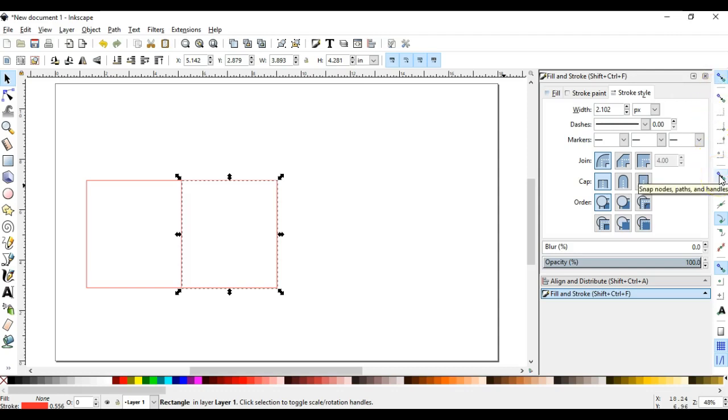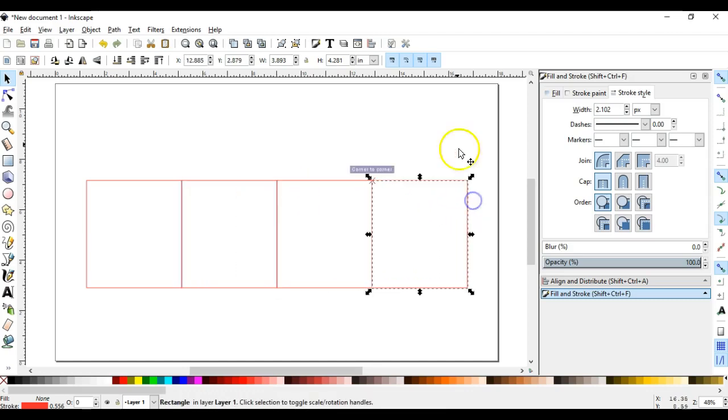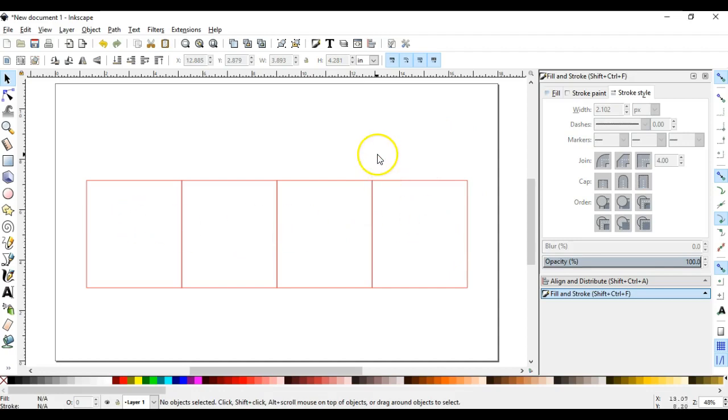You can enable snapping for several different options, like snap to corners, snap intersection, and snap to midpoints. I usually work with this off, but in this case I have it on. So I'm pressing Ctrl D. So now I have 4 walls.